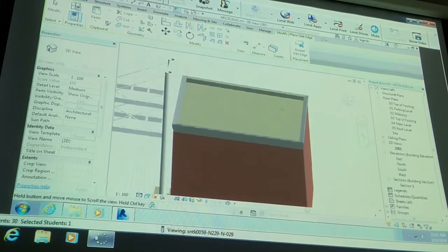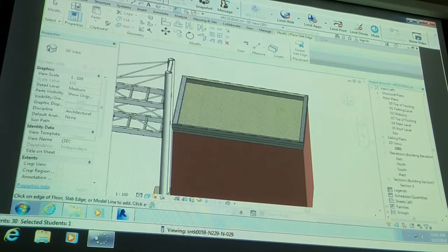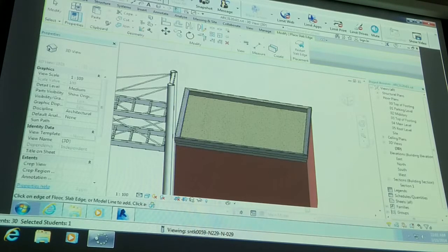No, there's no structural roof slab to it. So if you want to make a horizontal structural slab for your roof, structural floor is your choice. Well, you try to put in a roof hatch into the floor? I would just, is the roof hatch hosted by a roof? That is, right?